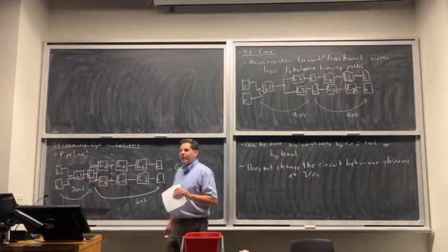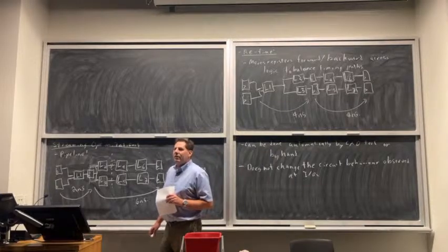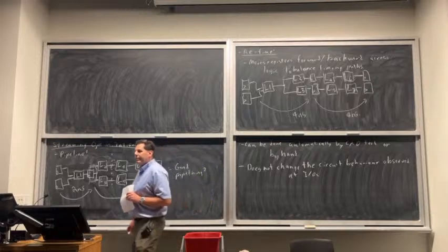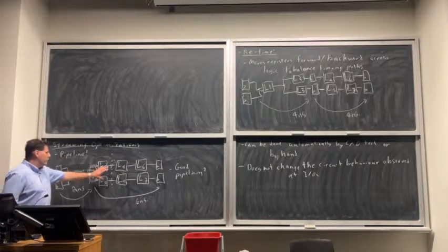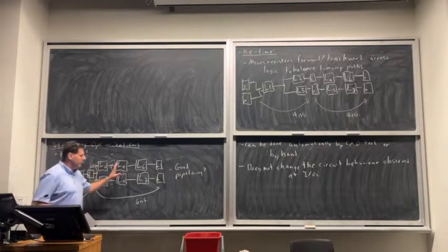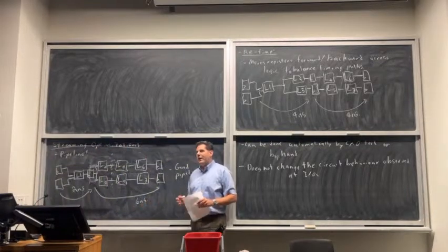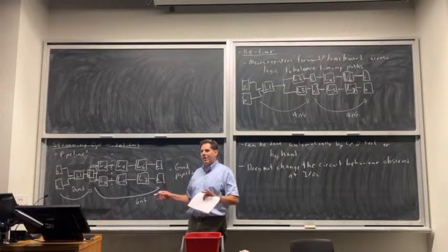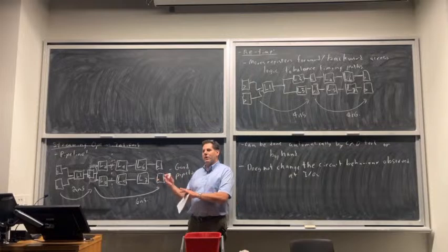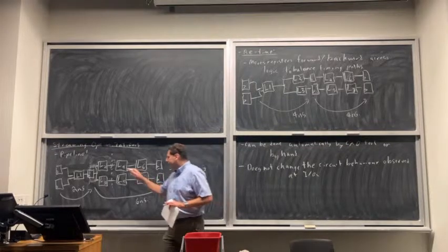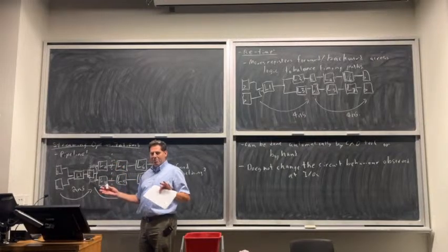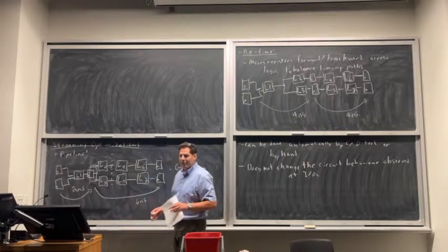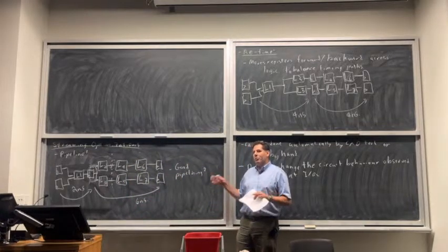Could you say it louder? I couldn't quite hear it. So you think it might hurt your propagation delay? That's essentially the algorithm screwing up, right? I'm showing you one here with just two sets of timing paths, and in a bigger circuit, there'd be lots of timing paths. A retiming algorithm is watching the longest paths and trying to optimize them. As I said, they do have delay estimates, because usually the retiming algorithm is running before the design implementation is complete, so it can make mistakes. So that's one reason. But even if your algorithm was perfect, there's a reason you want to turn it off.